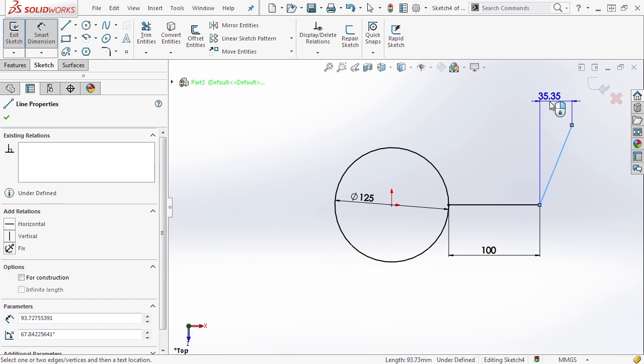One thing you'll also notice is next to the cursor, there's a mouse icon with a blue shaded right mouse button and a lock. Now, if you want to determine that this dimension should only be a vertical dimension, but you're having trouble because it's snapping to different types, drag it in an area where it's a vertical dimension, hit the right mouse button, and now we can lock it as a vertical dimension, but move it around the screen wherever we want. If we hit the right mouse button again, it'll unlock it, and it'll go back to a smart dimension that allows you to create multiple types.